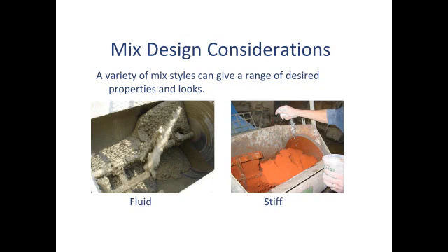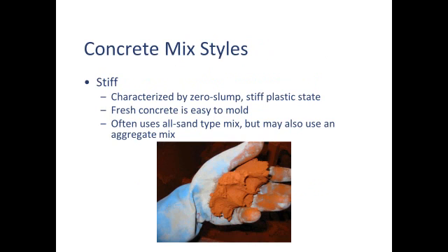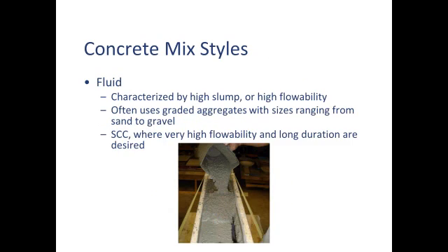look of your concrete. And stiff mixes, the simplest way to make a stiff mix is just to use less water, but sometimes you want other characteristics. You want it to be sticky, you want it to stay together, you want it to have a clay-like property, and there are some admixtures that can help you with that. So you don't always necessarily want fluid concrete. So this is what I mean by stiff concrete. And this is what I mean by fluid concrete, something that you can pour.